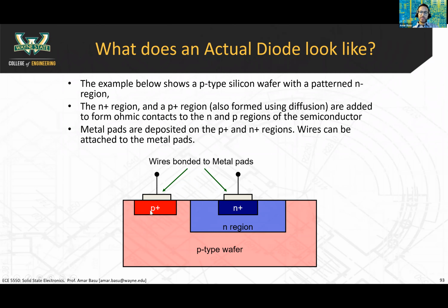Okay, and the reason for these P+ and N+ regions is because you can form tunneling type contacts. You can put metals above these P+ and N+ regions, and you don't need to worry about the work function of the metal. Because even if the work function of the metal is such that it would form a Schottky barrier, it doesn't matter because these highly doped contacts mean you're going to have a tunneling type contact. And it'll still behave as an ohmic junction.